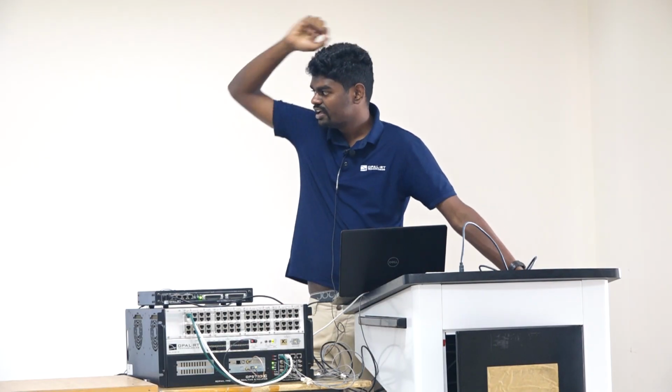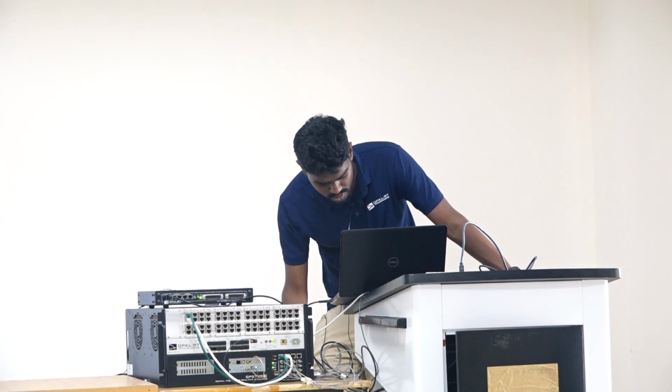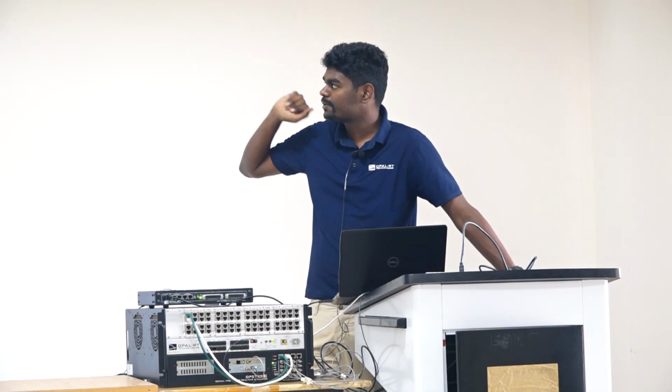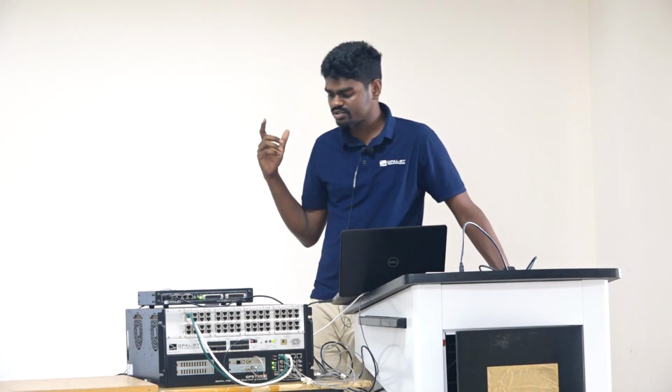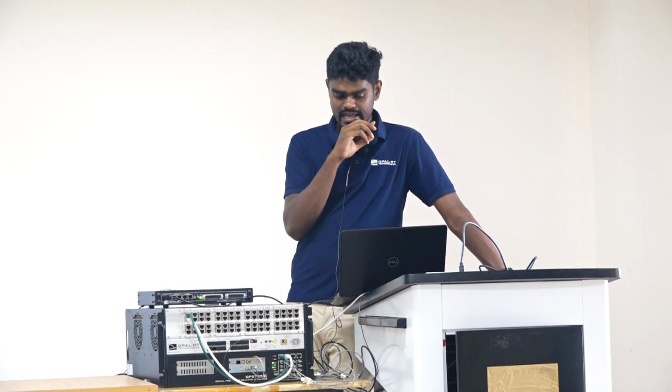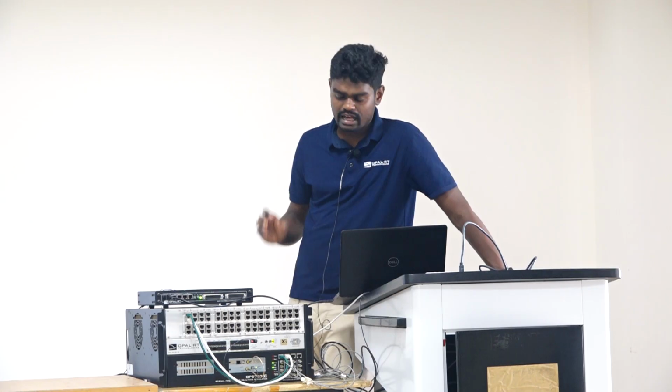You can see here, open Code Composer Studio. You can see that link. Through that, you will launch Code Composer Studio, and this window will open. Here you will have the automatic code which is generated. Now using this Code Composer Studio software, I'll be dumping it onto the controller. So here you have the debug option. If you click the debug option, the code will be loaded onto the controller. Let's wait.